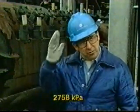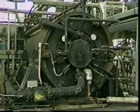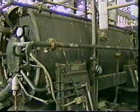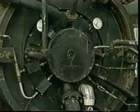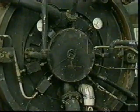Now let's look at the vertically split casing. Vertically split casings are used in most single-stage and higher pressure multi-stage applications. The design of the vertical split reduces the wall thickness needed to confine the high-pressure gas, and the smaller seams at the end plate allow for easier sealing.